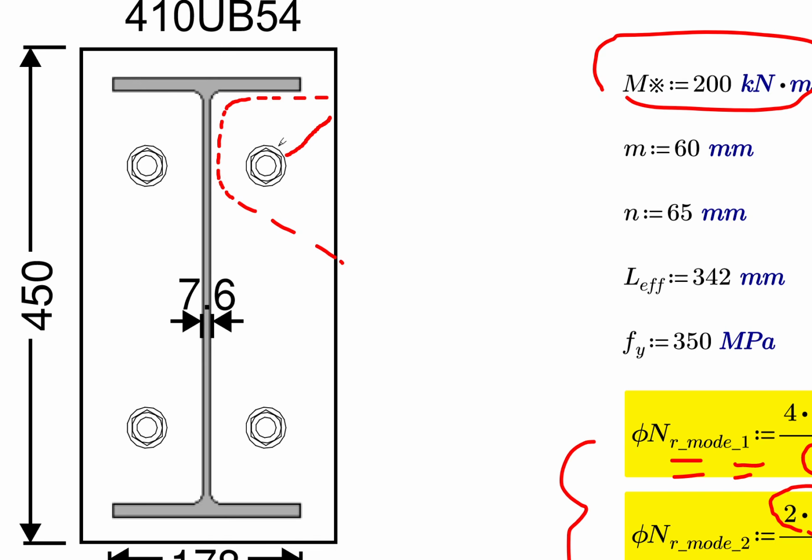Your positive yield line is going to be from the bolt looking down, where there are stretch marks, towards the negative yield line. So this portion of the steel plate is being pulled up, and it'll be mirrored on the other side, something like that.